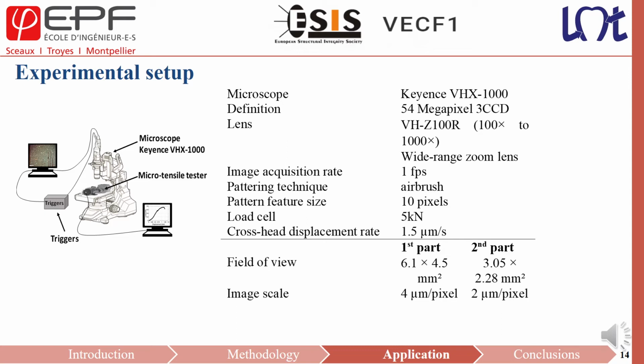Since the notch was welded, due to the temperature of filament deposition and the dimension of the notch, the magnification power was set to the lower length range value in order to monitor a wide enough region to contain the notch opening. When this opening was detected, a zoom in the vicinity of the notch root was operated with no interruption of the test. This is why images are divided into test part 1 and test part 2.